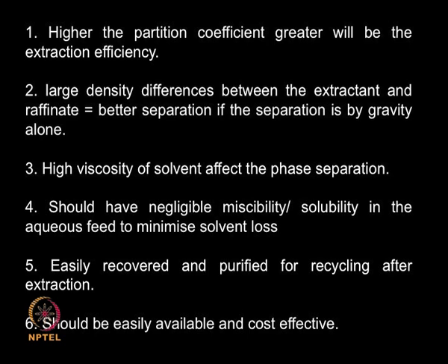Now you should be able to remove the solvent from the solute after the extraction, because your solvent has to be purified and recycled for further extraction. The cost plays a very important role in your downstream processing, and solvent recoverability is a main issue in the overall operating cost. The solvent should be easily available. We do not want to use many exotic solvents, because then it may be very expensive and it will add to the extraction cost.